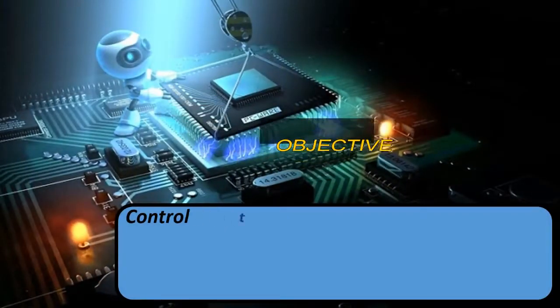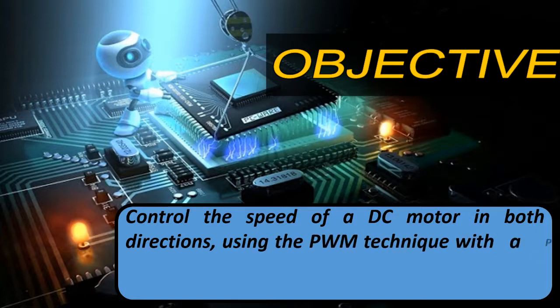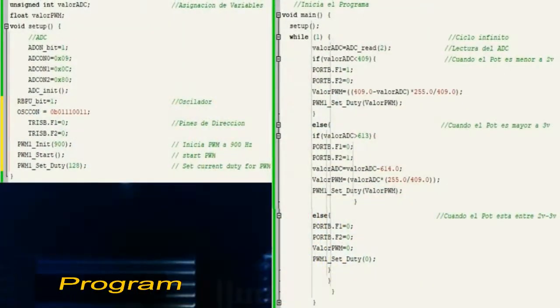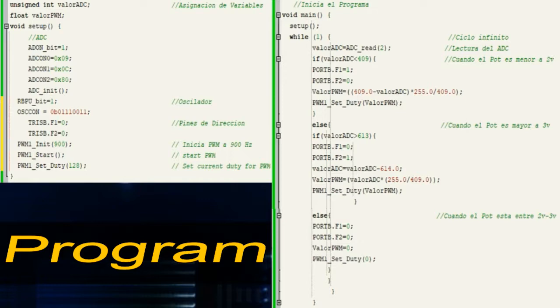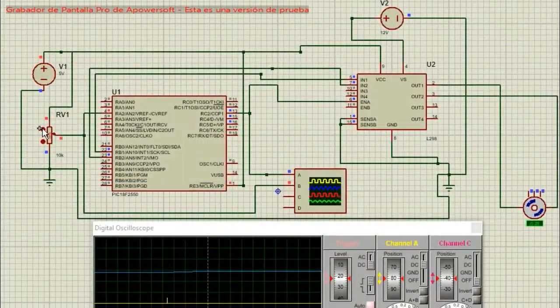For the second part, we have these objectives. Control the speed of a DC motor in both directions using the PWM technique with a PIC microcontroller. The control is exercised by means of a potentiometer. We carried out the programming of the new content based on the diagram shown in image 2, with some modification, which was to spin the motor in both directions, left and right.